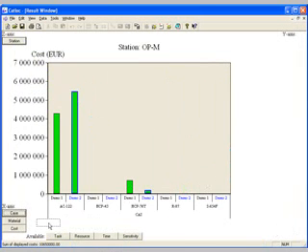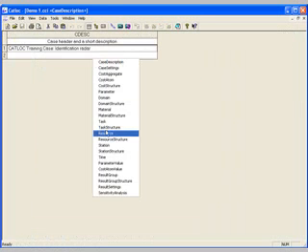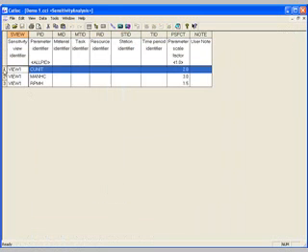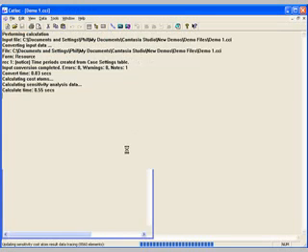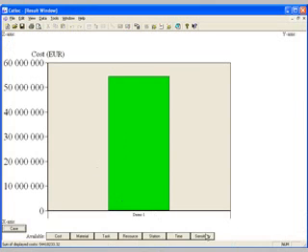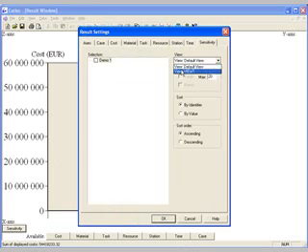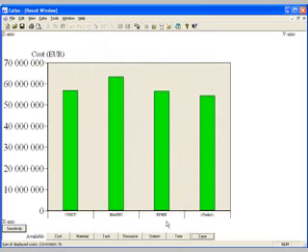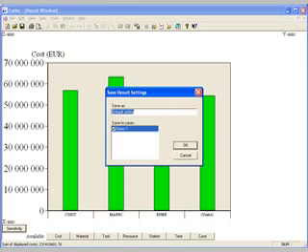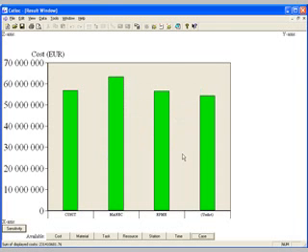CATLOC allows sensitivity analysis to be carried out as well. For example, consider a case where the storage cost per unit could be twice that of the quoted figure. In CATLOC, simply add and populate the sensitivity analysis table with the appropriate information, and select the sensitivity analysis run. The result is the ability to compare the impact of the changes with that of the original solution. The model can then be analysed in the same way as that already discussed. Any charts generated can be saved for later use or inclusion in a report. Likewise, all can be copied and pasted directly into another Windows program, such as Word or Excel.